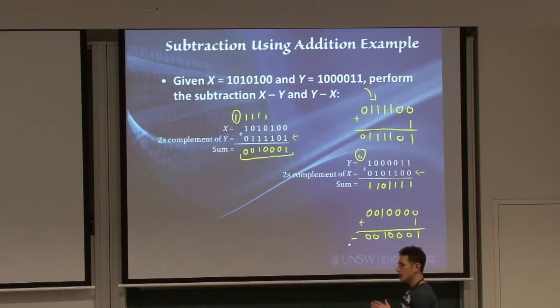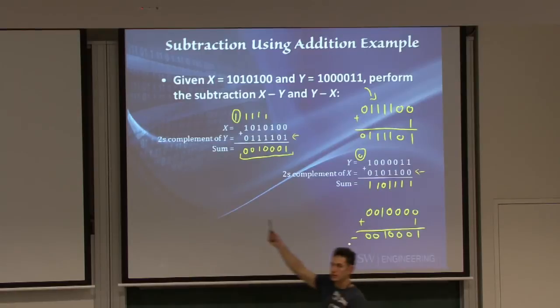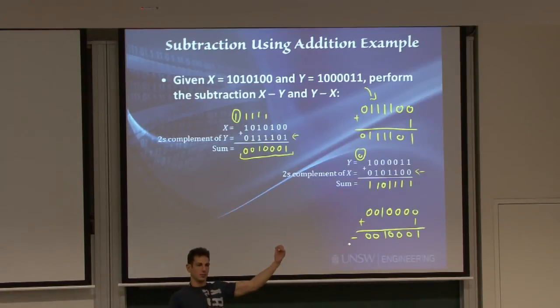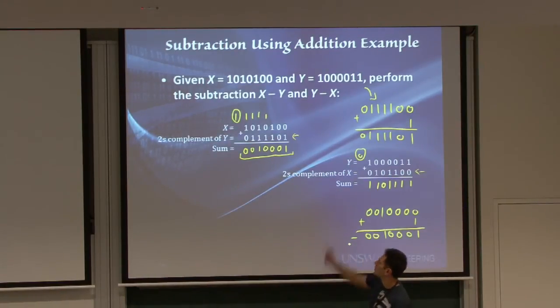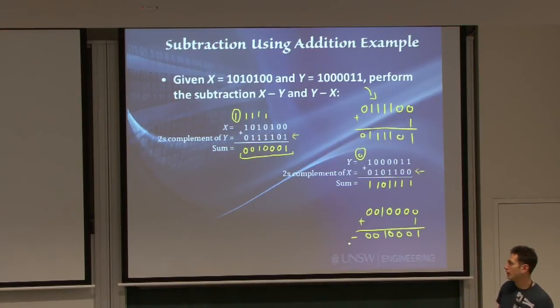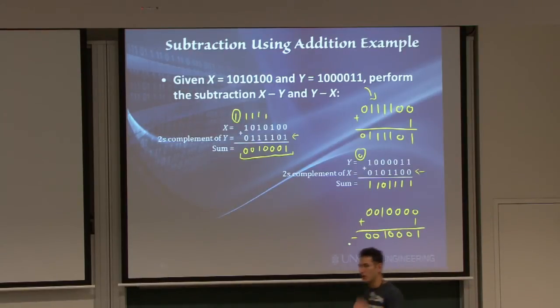So all the theory that I gave you comes down to this practice. And I think this is much easier to understand than to go back to the m's and n's and corrections and stuff. You just need to check whether you have a carry or not. And if you don't have a carry, just take the 2's complement and add a minus sign to it. I will say again, what we didn't talk about is how do we actually stick a minus sign in a digital design. On paper it's not a problem, you just put it up there. In digital design we only really have the 0's and the 1's. We need to find a way to actually put the minus sign there.